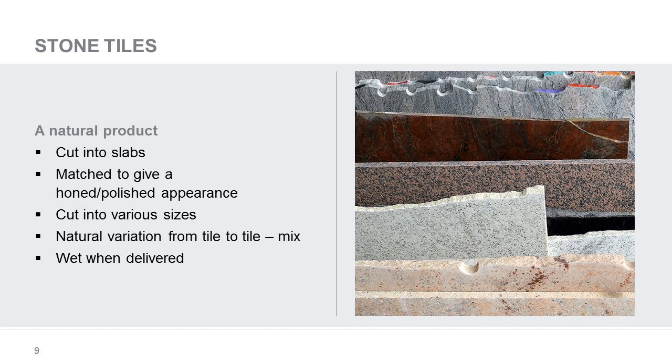Every natural stone will have a unique appearance due to the natural variation of tiles. It's important to ensure a sufficient amount is specified in one batch and that the tiles are mixed so that the shades are blended effectively. Some stone tiles are also packed wet, so they will need to dry out.